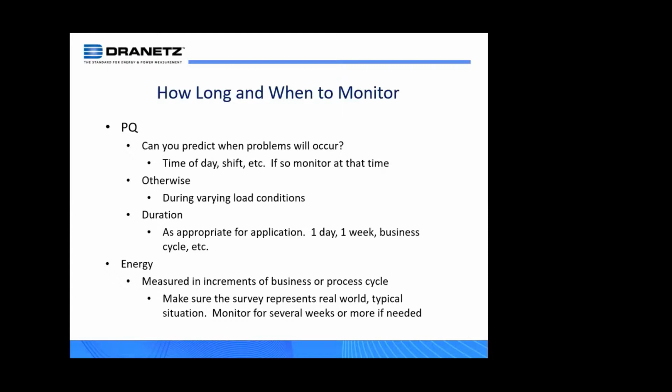But generally what we find for PQ monitoring, it's usually a week. You put it on a week and collect the data. Or sometimes you'll see scenarios where you put the power monitor on and you leave it there until something happens. And that can be a day, that can be an hour, it can be a week, it can be a month. So it depends on the application.